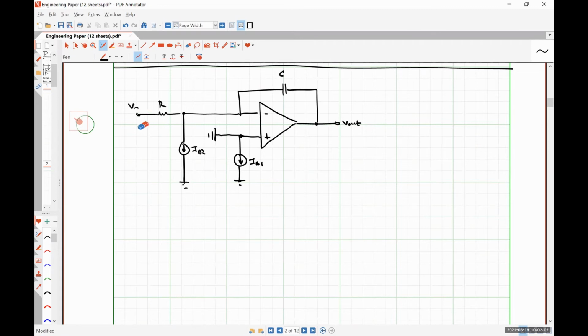So let's look again purely at the effects of what the bias currents do without any input signal, meaning let's ground this guy. We should again be able to observe that our current IB1 has no effect on the output of our amplifier, right? We're just having current flow in this little ground loop over and over and over again. So that's where all that bias current goes. It's just hanging out around the ground.